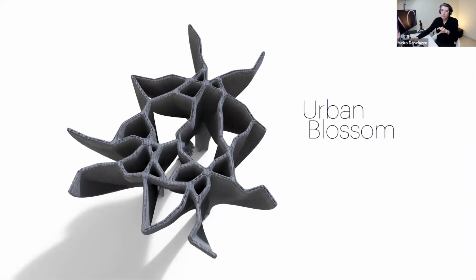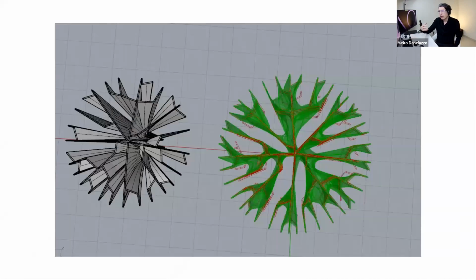So what we tended to do here is to define the system. And again, this system is using 3D printing, but again, the previous technology, so the contour crafting, with geopolymers, using sand as main material and geopolymers as binders. Here, the idea was, because in this region we don't have the problem of rain, so we don't need to cover from rain. So the idea was to create a shelter, a protection from the sun.